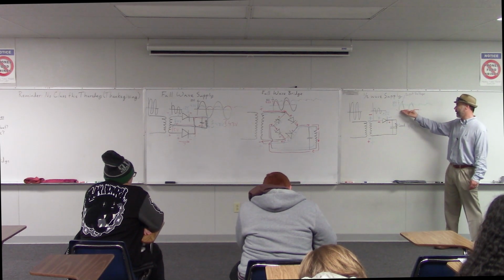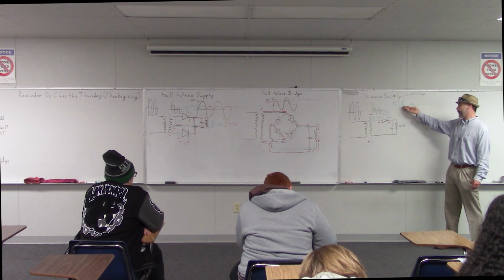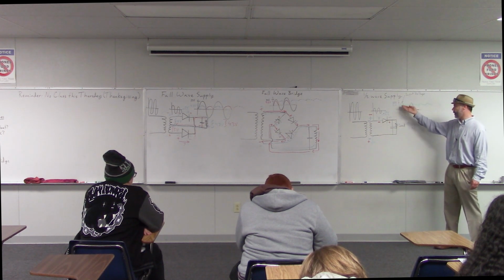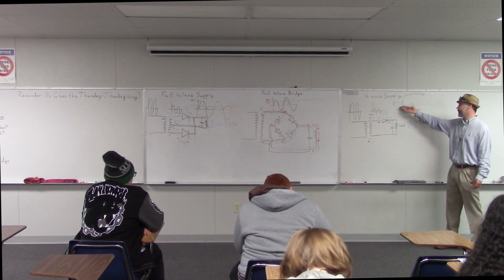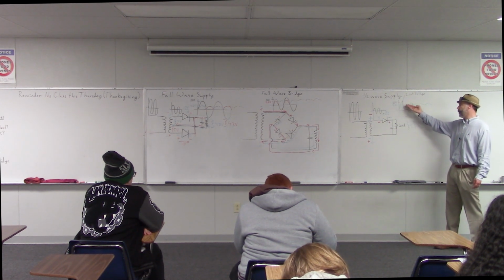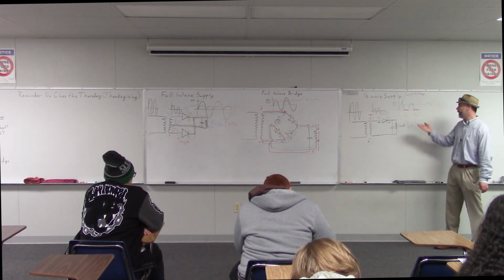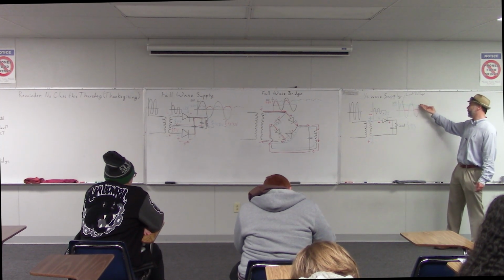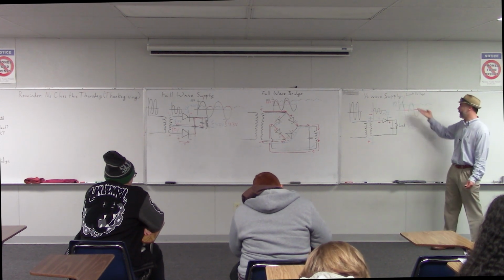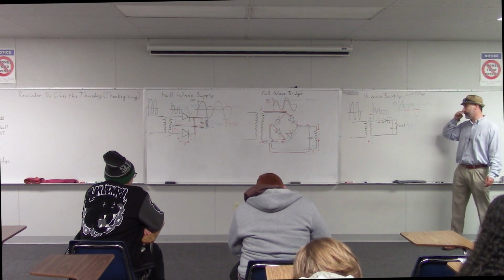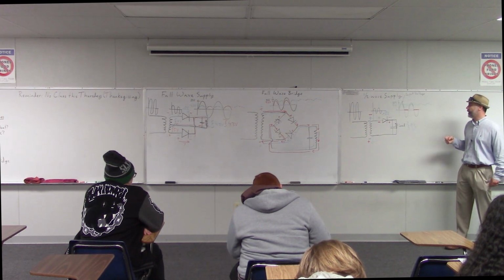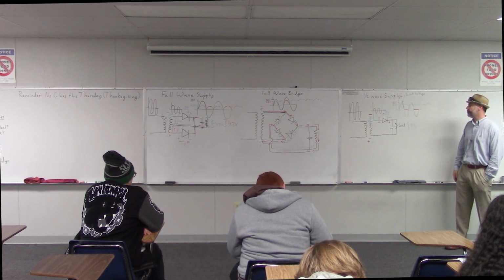Also, you've got a long time for the capacitor voltage to discharge. Even when we're using a capacitor, there's a long time between these humps. So the voltage can discharge more over a longer time, and so you get bigger ripples there. And of course, we don't want any ripples. We're trying to get a nice flat signal. So those are a couple of disadvantages of the half-wave supply.